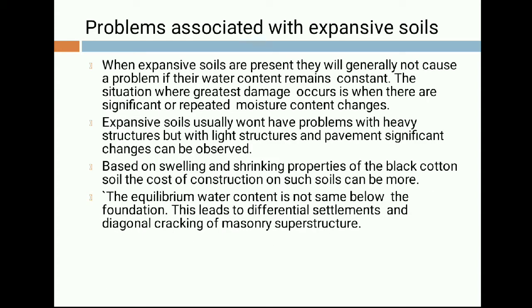Now, which are the various problems associated with expansive soil? When expansive soils are present, they will generally not cause a problem if their water content remains constant. Means there will be no problem if there is no moisture variation in the soil. But the situation where the greatest damage occurs is when there are significant or repeated moisture content changes, that is, if the amount of water variation is more, or the wetting and drying cycle is more, that part is more prone to the swelling property of black cotton soil.